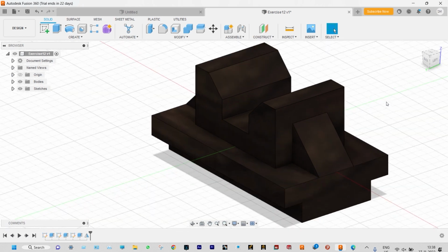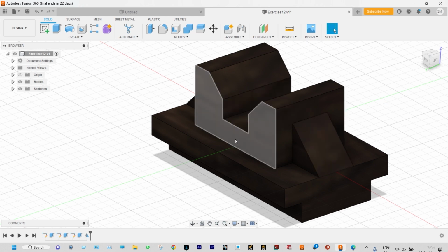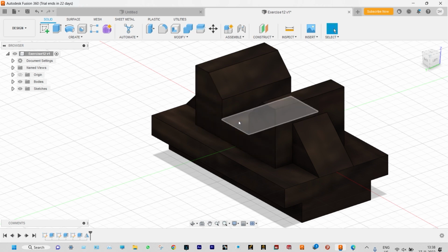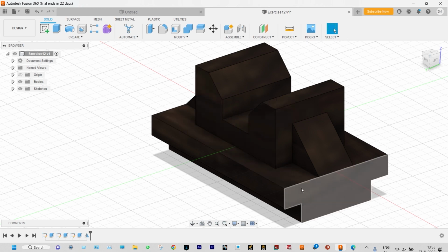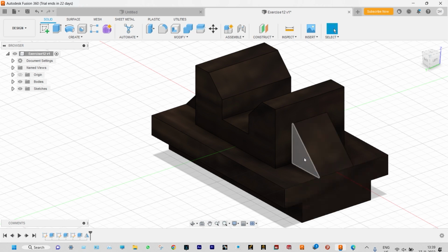This was a very simple modeling, and we started this modeling from front view. We made a hub of this one, and next to that we applied a mirror of this one to make the complete view. And again we started with the side view. On the middle plane we have provided this sketch, and that was extruded to a depth of 100 millimeter. And finally from the front side we made this triangular shape at the middle plane, and that was extruded symmetric way to a depth of 20 millimeter. And finally this object was mirrored on the other side.